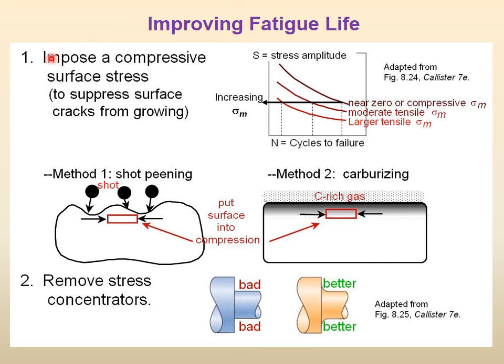Now, this we have not talked about. Let us see first. You see, when we were doing the fracture toughness test, you had a compact sample with a V notch, and then we were applying the load, right? The load was in mode 1, right? Mode 1 is also called what? Opening mode. Why? Because the tensile load is at 90 degrees to the crack surface.